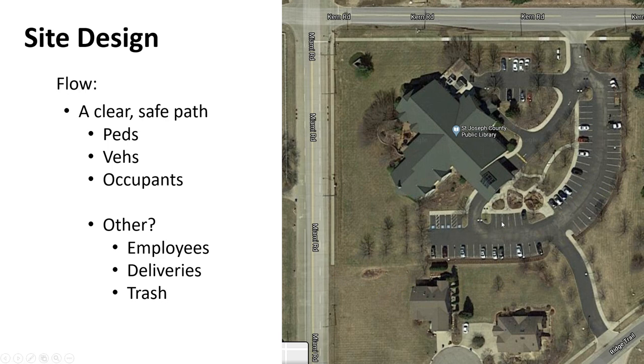So that's thinking of all of the users and how they're getting in and out of the building. Now, if this was a commercial site, now we would think about trucks. If this was our delivery area and we're going to have big trucks, where do the big trucks come in? Do they have adequate space? Can they turn around? How do they interfere or not with other traffic and with pedestrians, right? And as you can see, we often put loading docks in the back so it stays away from general users and particularly pedestrians, right?